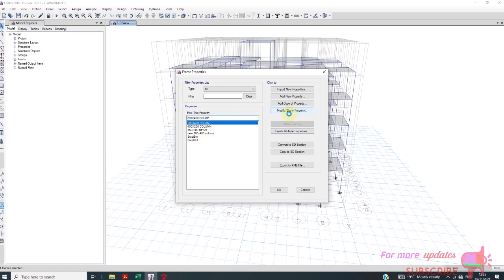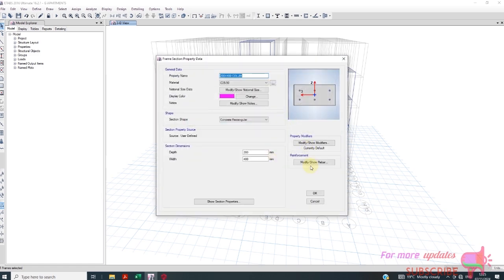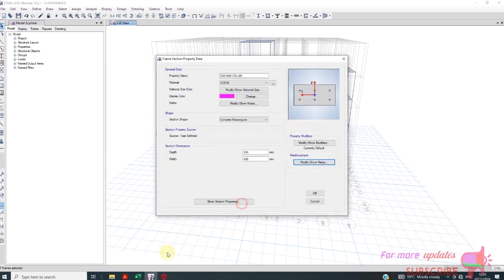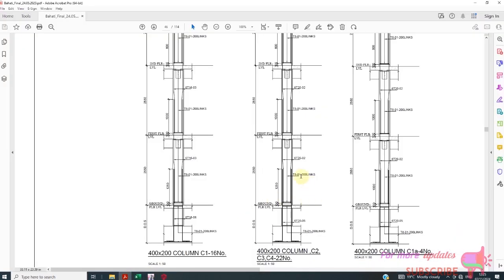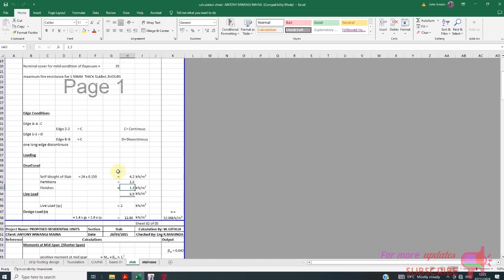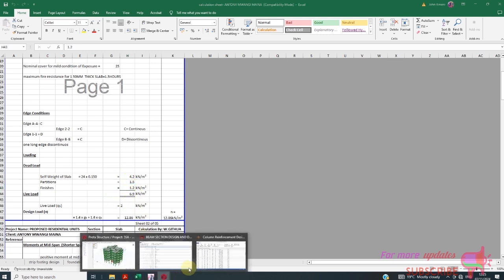So modify. Have these columns. That is T16, 4 corner bars and 2 intermediate, T16 and T8 at 200, as we have used in this affordable T8 at 200 links. This is probably by government of Kenya. So we are going to use it as our reference. We're going to use a suggestion from Prokon Structure as our reference, and this manual design from another engineer as our reference.